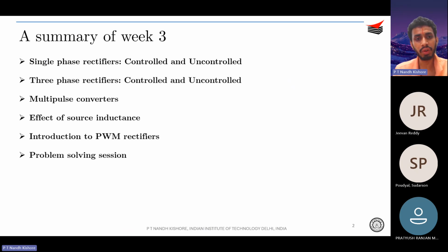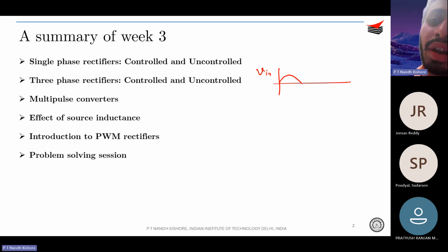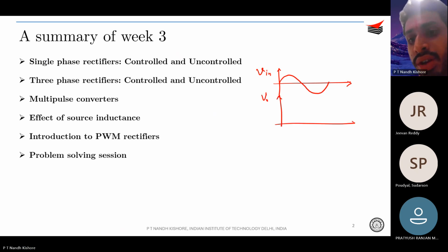So you study rectifiers, you of course know that the power factor is going to be very low. The power factor is 0.9 cos alpha or something like that for diode-based rectifiers. So the emphasis in power electronics research is on how do I do rectification while maintaining my input current to be sinusoidal, correct? So the idea is, let me first disclose the idea. You have an input which is purely sinusoidal, a pure sinusoidal wave, and you want the output to be a flat DC. So this is something you want.